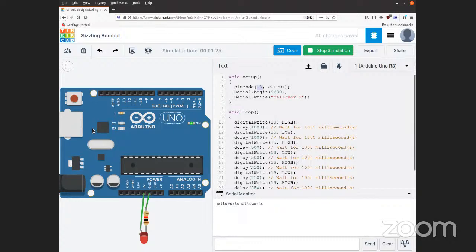All right, and since nobody has said anything about needing more time, I'm going to give you a quality of life tip. Now that you've hopefully modified your program, what are you going to do if you want to change it so that you're writing to pin 12 instead of pin 13? Now you have to change the number on every single digitalWrite statement. In fact, what if you forget which pin you want it to change to? Then you would have to test out which pin is actually the right pin that you want to change to, and this would be unnecessarily wasting time.